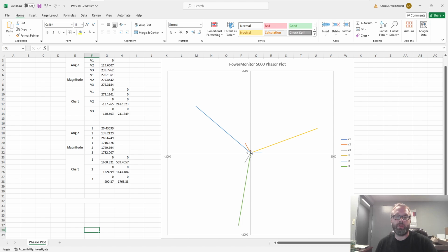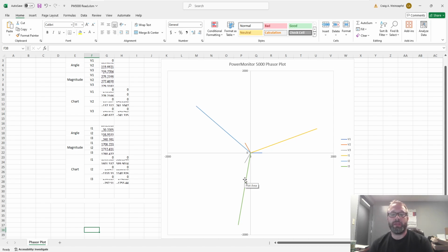which is actually rotating counterclockwise or clockwise, which is opposite of convention. That's what the negative sequence current was, why it was being called negative, because the order of the voltage went A, B, C, and then the current went in the order A, C, B. So it said, okay, you have 1700 amps in negative sequence current. And that's really what led us onto it. And then we found out, okay, hey, these were misapplied, misinstalled.